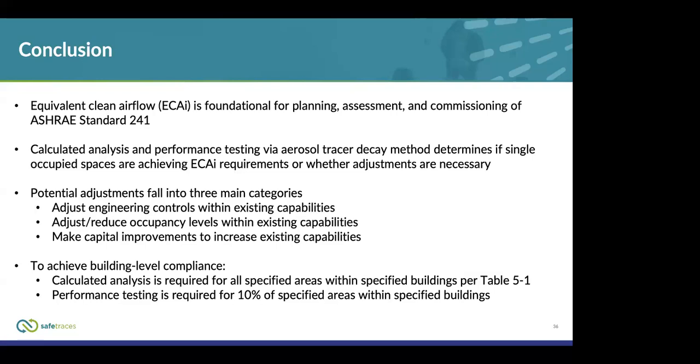To level up to building level compliance, as I said, you do calculated analysis for all the specified areas per table 5-1, and then performance testing in 10% of the specified areas within the buildings. So that covers it. We now have about 10 minutes or so for Q&A.